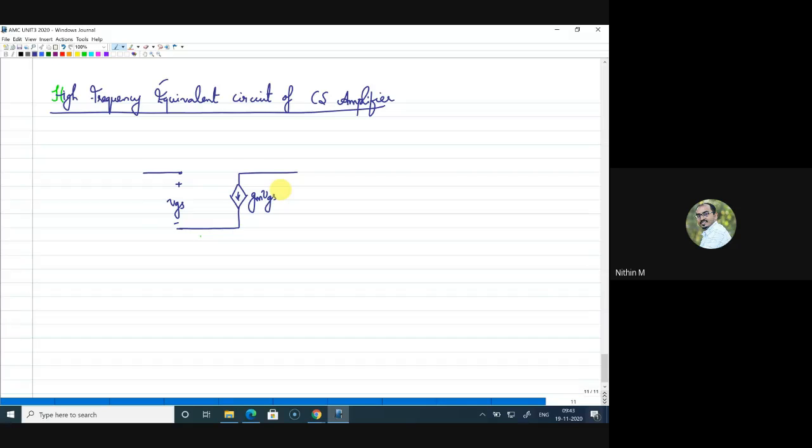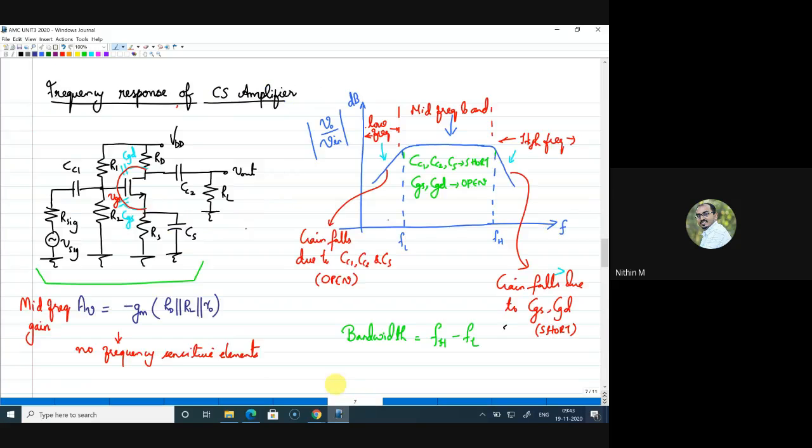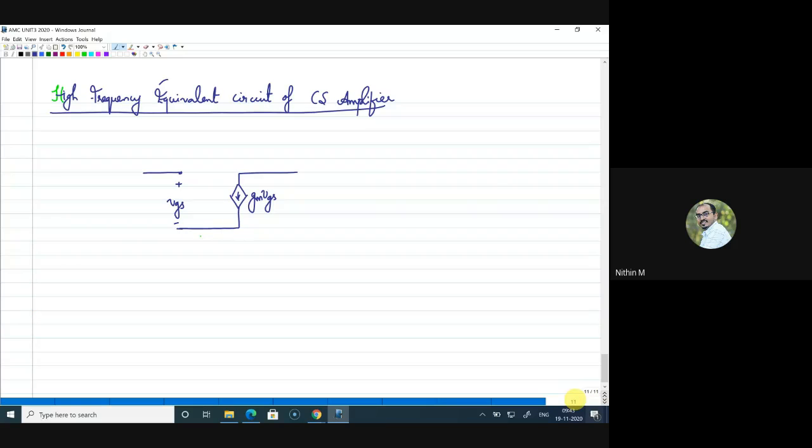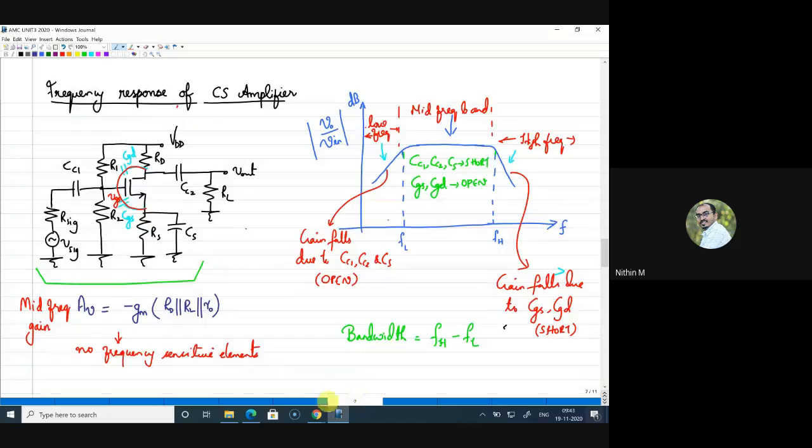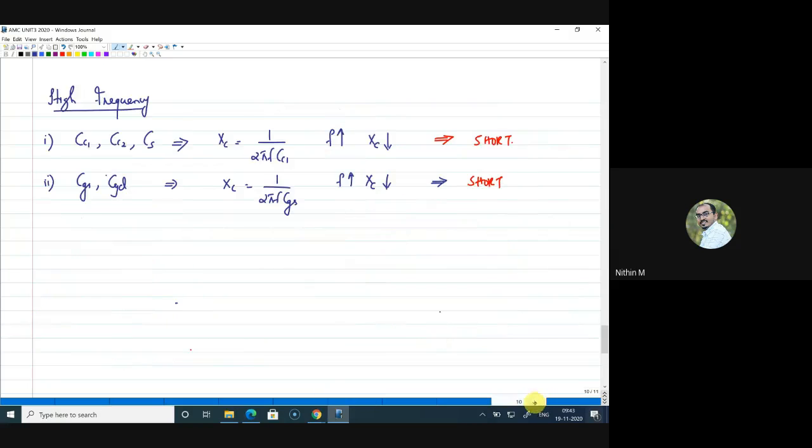Okay. Now what I'm asking is with respect to the circuit diagram I'm showing here. Yes, go ahead. Sir, RS we can draw at the source. Okay, will there be RS there? With the capacitor it can be nullified. Yes, because at high frequency, even the capacitor CS is acting as a short, right? That is what we just discussed. So RS will not be there.